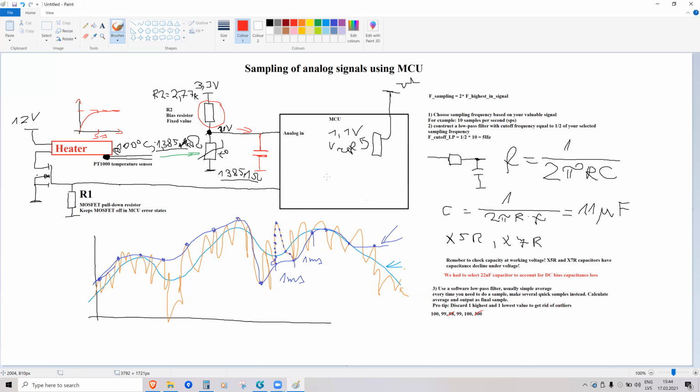And then, for example, in this heater case, on each signal, you would either use an on-off control or a PID controller. Usually people use proportional integral differential, PID.